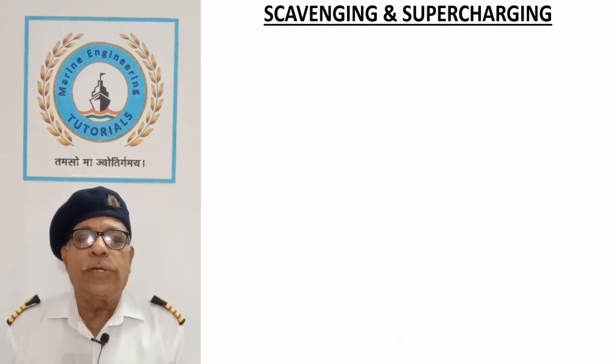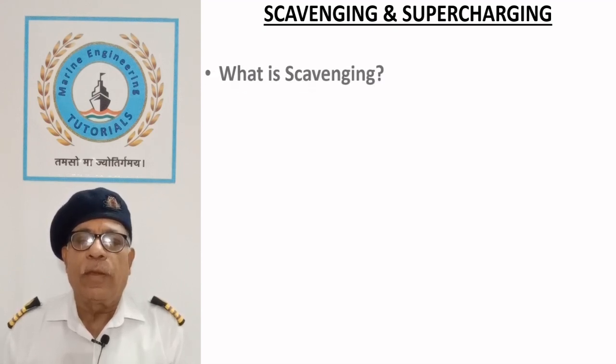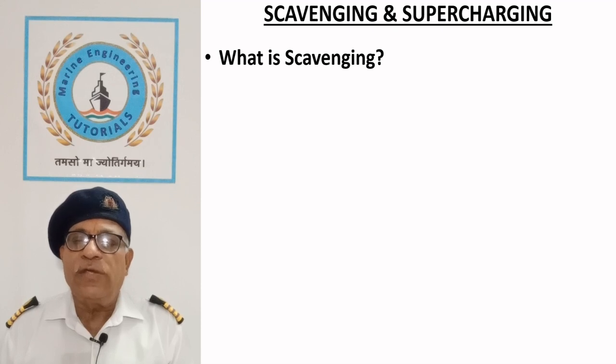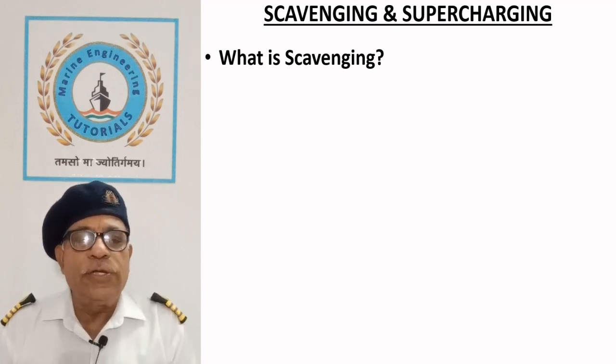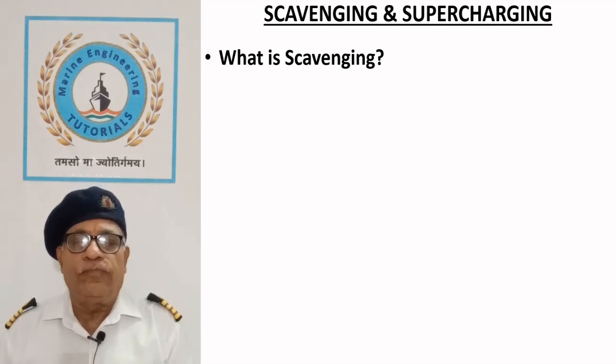Scavenging and supercharging. What is scavenging? Scavenging is an essential process in two-stroke marine diesel engines used for ship propulsion, which supplies the engine cylinder with fresh charge of combustion air for the next cycle and drives out the exhaust gases produced in the previous cycle.